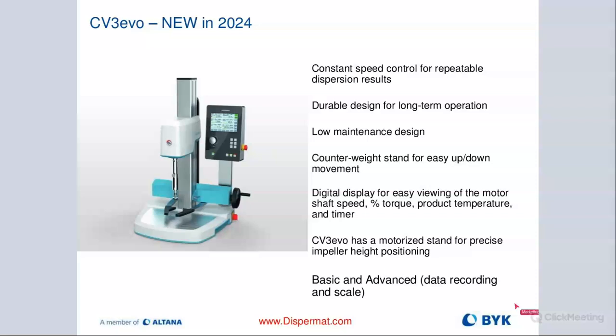and only then will the machine give you clearance to actually start running. And then if the container is clamped properly, you're setting H1, H2, which are the reference points I mentioned earlier for upper and lower limit. That means that you can then safely operate the disperser in between those two reference points. If the blade would be outside of the container, outside of these limits, then the machine would also show you on the display that you're not safe and you cannot run the machine. It will not even power on.